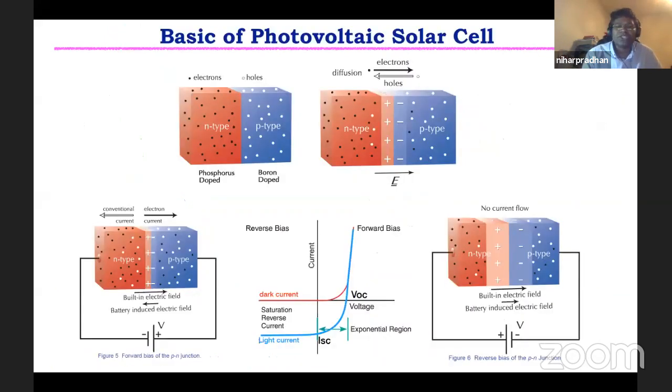for. Since we will be talking about the photovoltaic solar cell in this talk, I will go through a little of the basics of the photovoltaic solar cell, particularly the PN junction solar cell. When you talk about the PN junction solar cell, we have two different kinds of materials. If you look at the silicon solar cell that we are using today, we have an N-type or N-doped silicon region, and we have a P-doped region, which is hole-doped using boron. Then when we put them together, it will form a PN junction of N-type and P-type material.